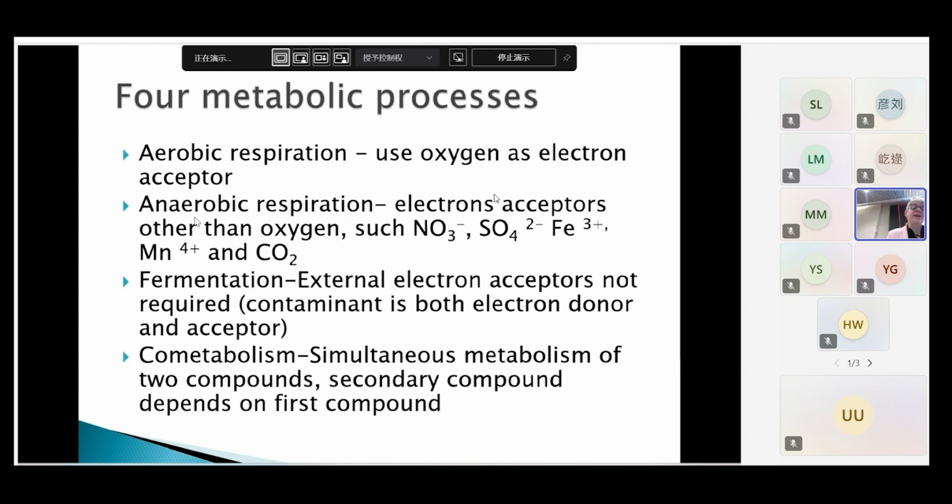So this toxicity characteristic leaching procedure is kind of the test that's used. You crush the material, you treat it with acetic acid, you filter it and so on. And then you compare it to these levels. If any of the contaminants exceed these levels after the treatment of the leaching, then you still have a hazardous material. If it's lower than these levels, then your method is now successful.